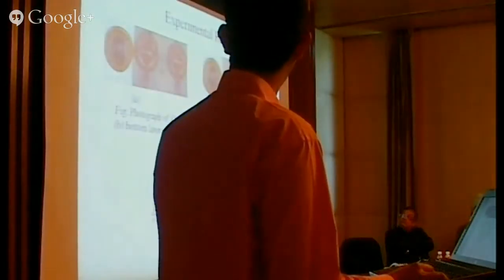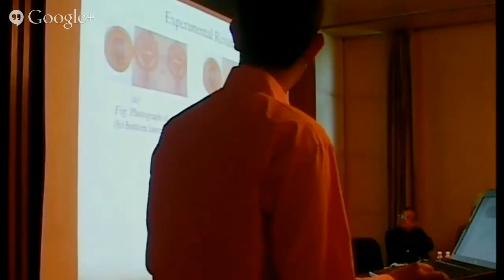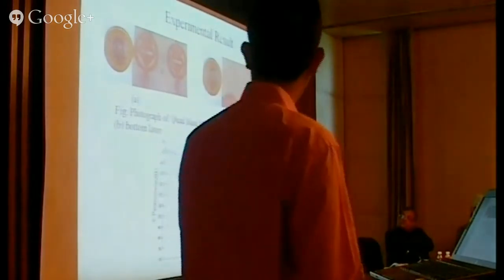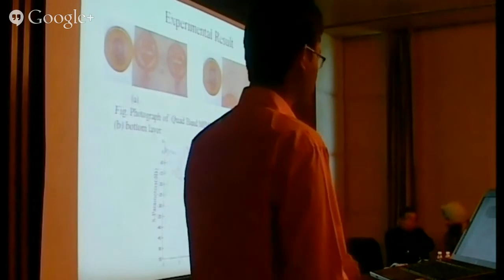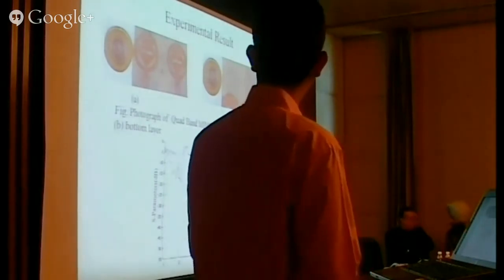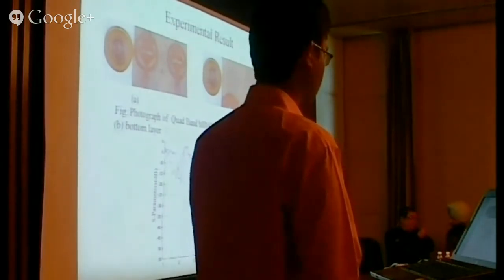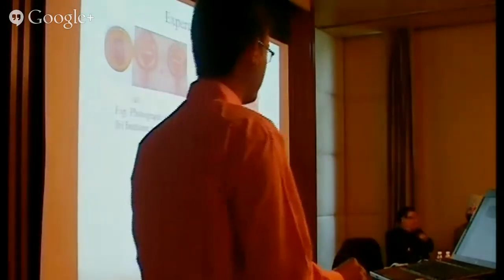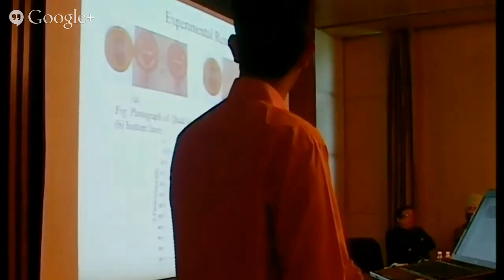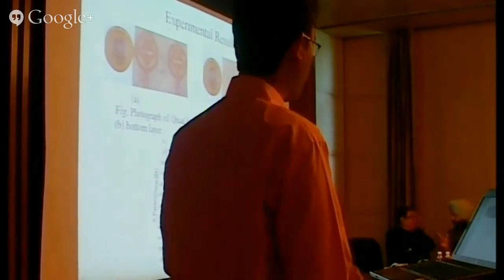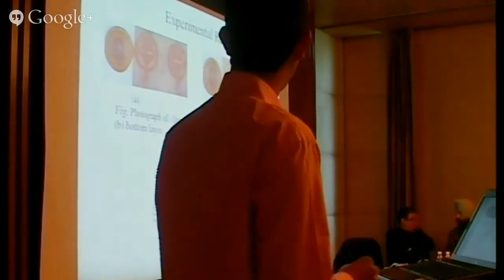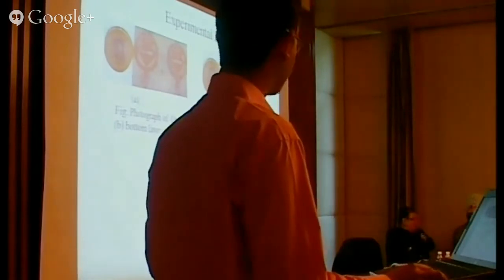This is the photograph of my fabricated antenna, and it is observed that the measured results almost match the simulated results. But in some cases, some differences are found between the simulated and experimental results. It may be due to fabrication imperfection or the tolerance of the dielectric constant of the material.